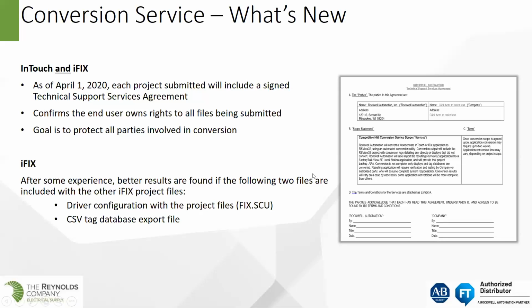We highly encourage you, if possible, to provide an external CSV tag database export of the iFIX database, as well as all the driver configuration files that you have. That just makes things go smoother along with the conversion. So go ahead, next slide, please.